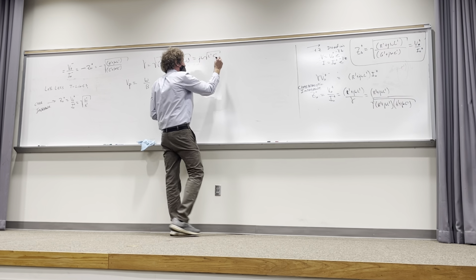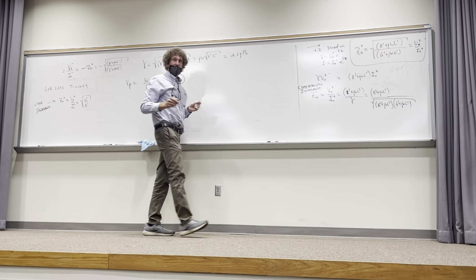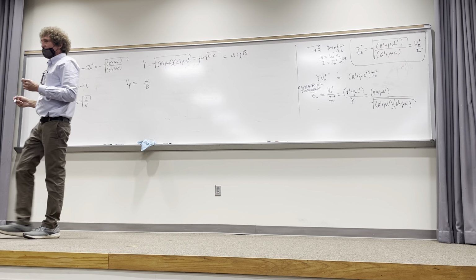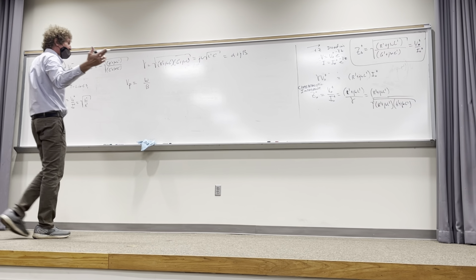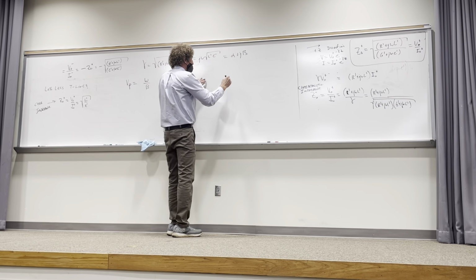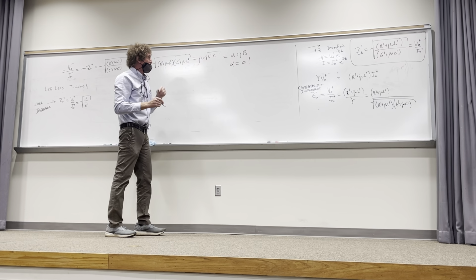Now what is gamma? That's alpha plus j beta, correct? So what can you conclude about alpha for a lossless line? It's 0, right? There's nothing there. Do you all follow me? The coefficient, there is no real part but 0. So alpha, if it's lossless, is 0. Makes sense. What is beta?